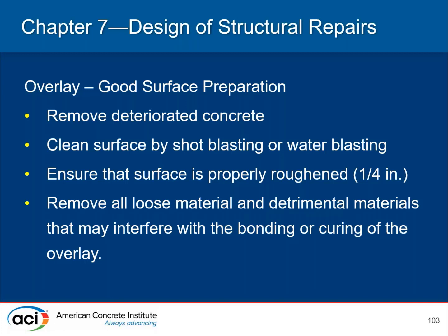But conditions can be highly time sensitive with that respect. And also the large area that has to be confirmed to have good surface preparation. So it can be somewhat challenging to do a bonded overlay unless very good quality control and good specifications are included. Removal of deteriorated concrete is of importance, obviously, because attaching new overlay material to existing structure is going to be dependent upon the capacity of the area to remain.